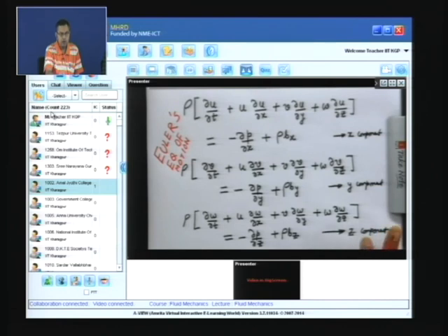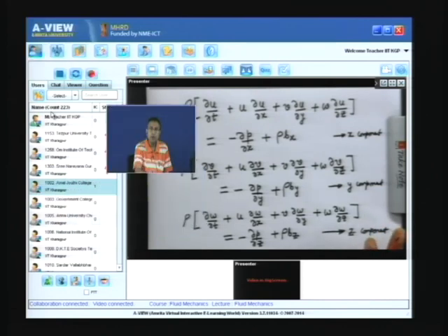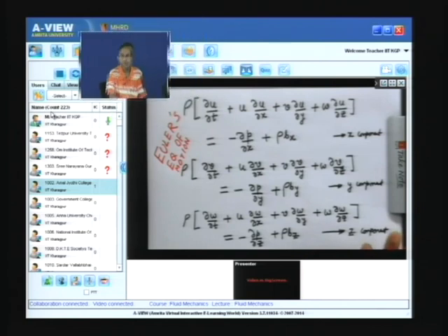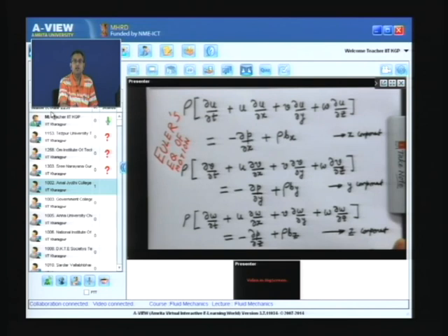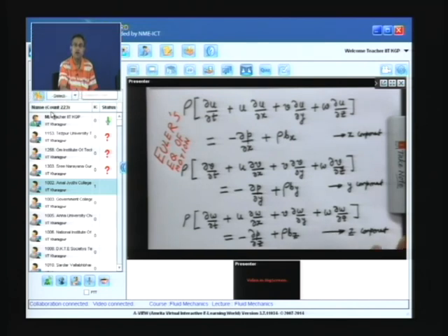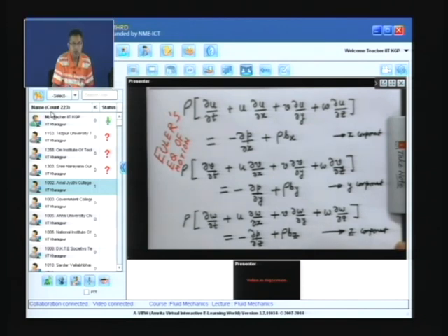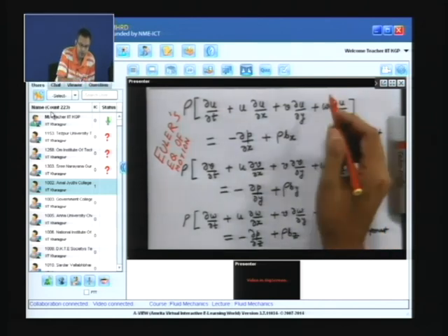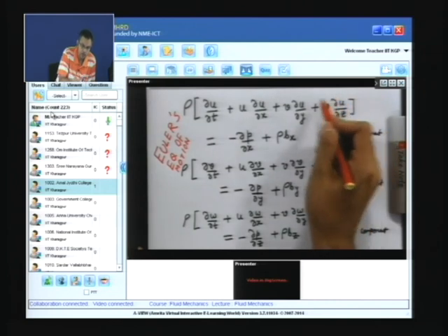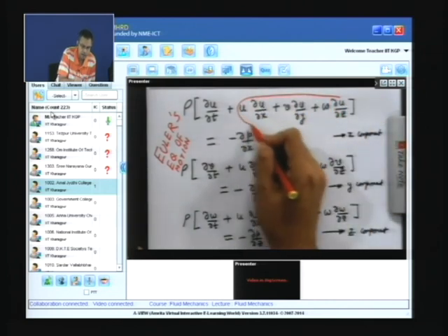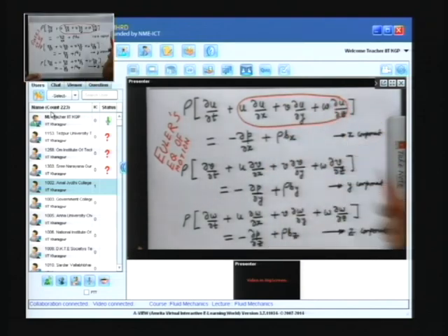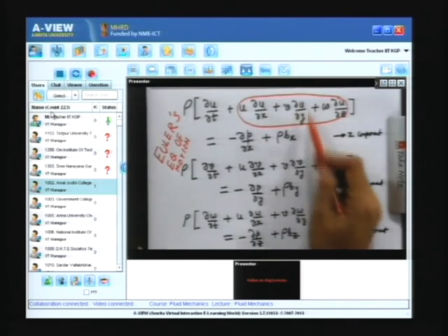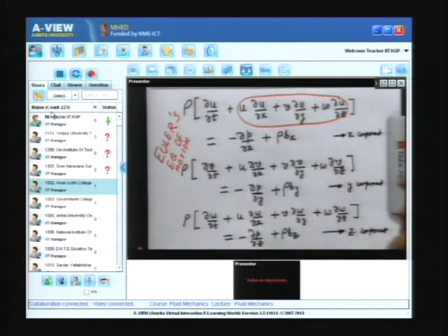So, Euler's equation of motion, what is the assumption that goes behind? Remember, whenever you are teaching some equation to your students, always emphasize on the assumptions under which that equation is valid, because all equations will not be valid for all cases. So, Euler's equation of motion is valid for inviscid flow, that is the restriction. Now what we will do is we will see how to write this in a compact vector form, u del u del x plus v del u del y plus w del u del z. So let us do that in the next sheet of paper.